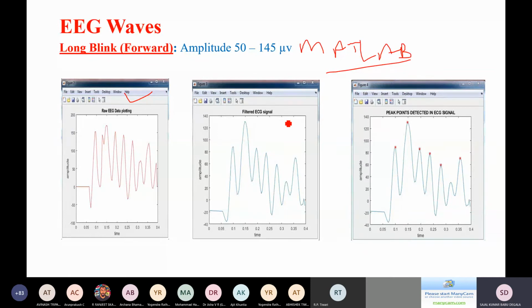If you have a MATLAB version of 2013 and above, 2016, 2018, 2019 or 2020, you are going to get an add-on option. In the add-ons, you can add the Arduino board and Raspberry Pi boards. Once you add the boards, you are going to get the blocks there. Using those blocks, you can easily control the Arduino and transfer the commands from MATLAB to the Arduino board.